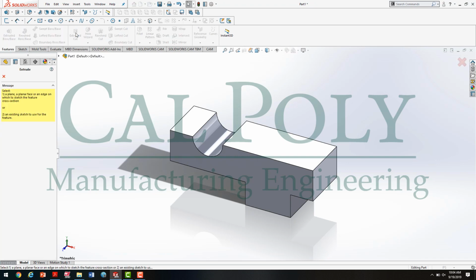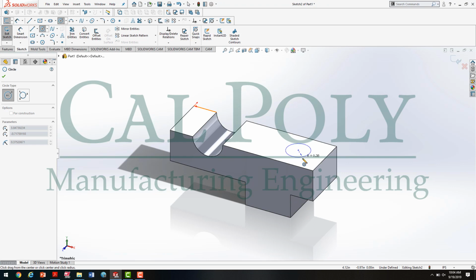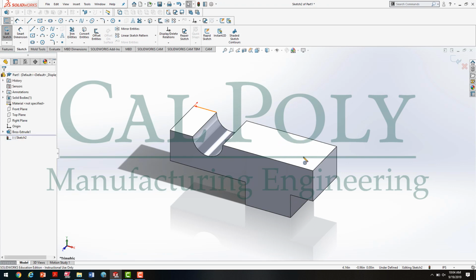So when I click Extruded Cut, it's asking me to click on a plane on where I'd like to make my cuts. So I'm going to click on the top plane of the part. Now you'll see the 2D sketch tools are active, and I could technically start sketching in the isometric view like you see right here. But I'm going to hit escape in that tool real quick and change the view normal to my face. So when I hit spacebar, I can actually pick all the different views right here.